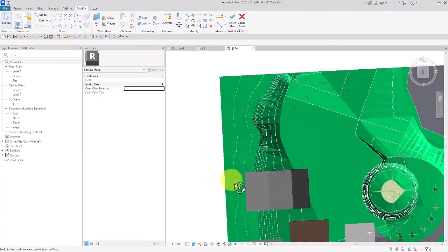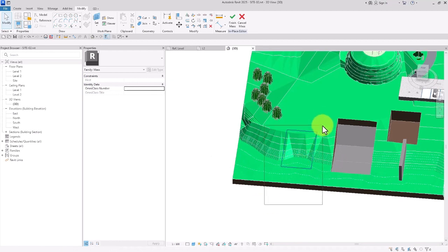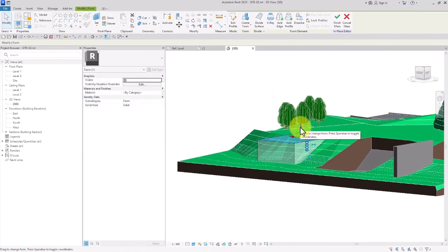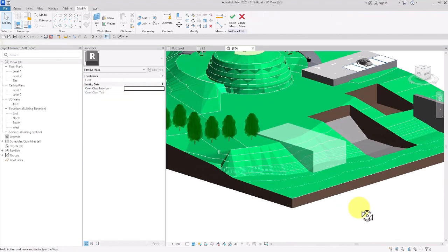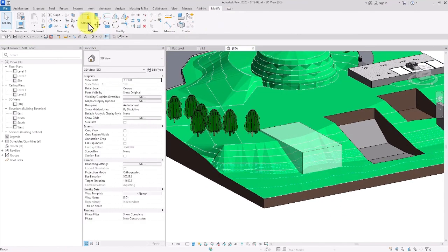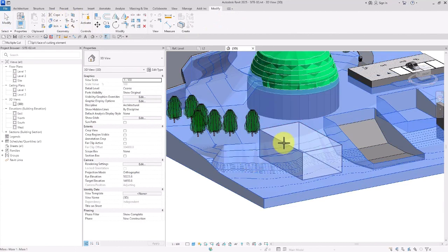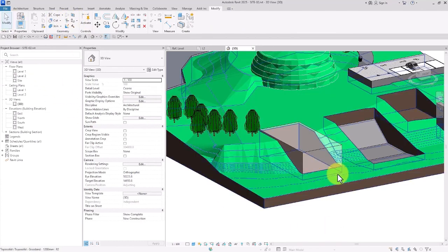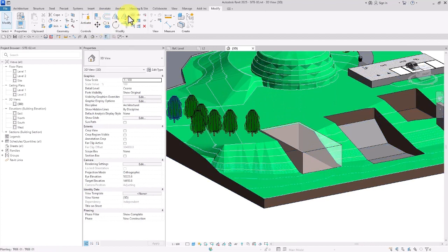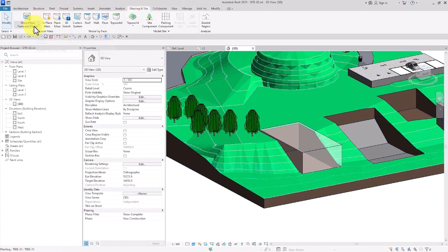Yeah, this will do. Now, I'm going to select this and then convert it into an object, into a volumized object. Now finish and then select cut to cut this out of our topography. Again, we had this technique in the previous version of the software, and we could have also used void to do the exact same thing here. Now let's see what is different about Revit 2025.